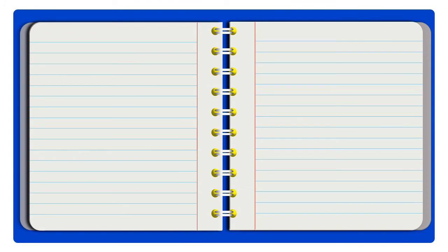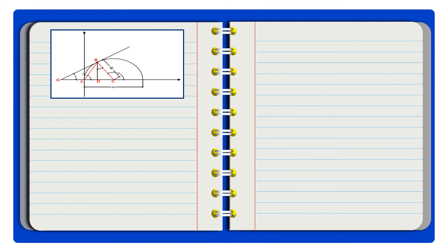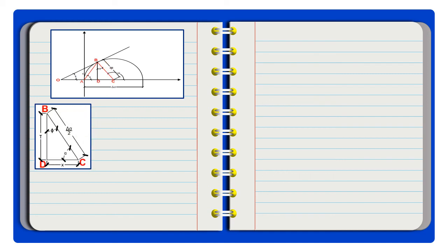Now that we have the cohesion and angle of internal friction, let's go back to the Mohr-Coulomb failure diagram. What we need to determine now is the stresses on our failure line, or stresses at failure. That is at point B. So, here we will use triangle BCD, since it includes the shear stress that we need, which is the shear stress at failure. So, extracting triangle BCD, here it is.